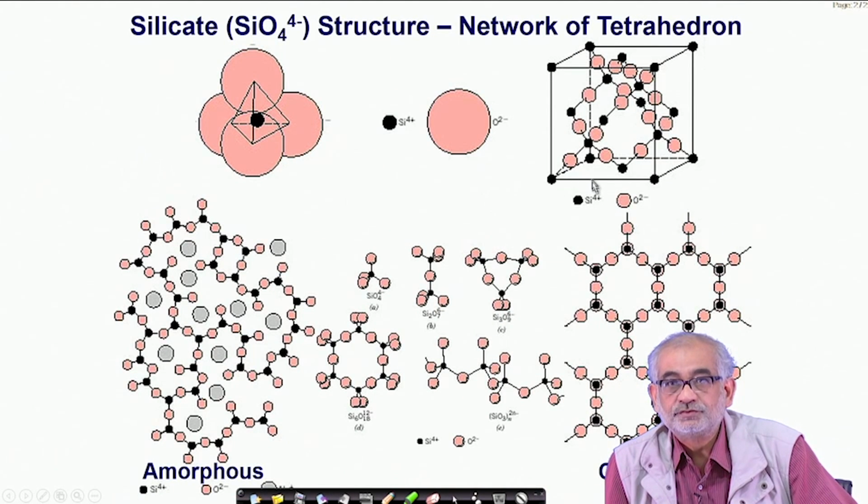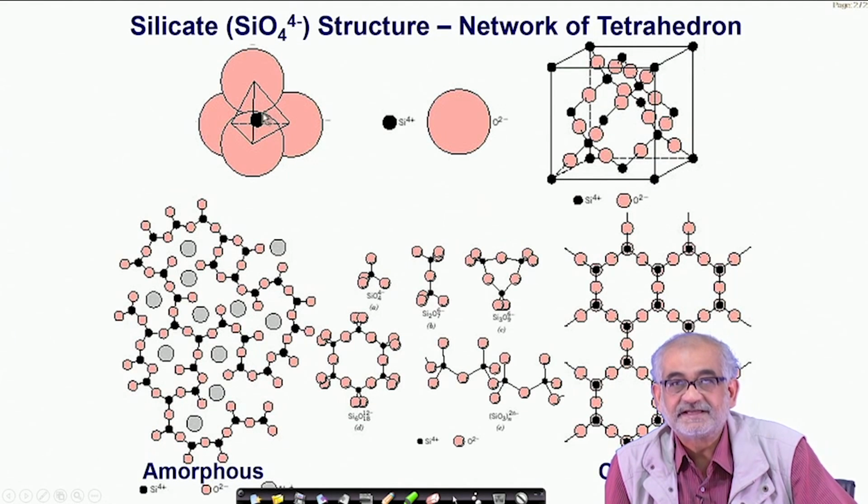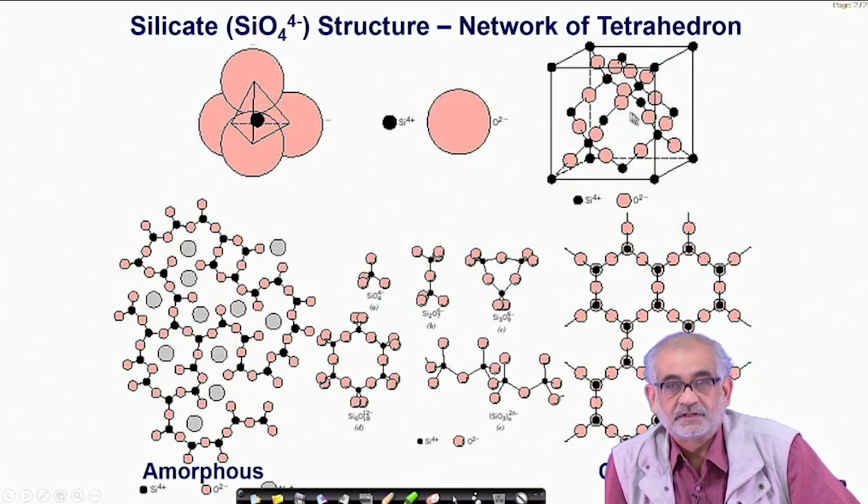Now we are moving into non-crystallinity. So, for example, imagine that we have a silicate tetrahedron, simply a tetrahedron where I have a smaller species in the middle and 4 bigger around. If this is a single unit, I can actually pack this unit in 2 possible ways. I can pack them in such a way that the center, this dark one, coincides with one of these dark spots shown here in this particular cubic lattice, cubic unit cell, such that the other ones automatically follow a certain trend, and in the process the whole structure will manifest itself as a crystalline aggregate.